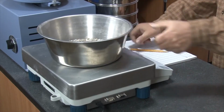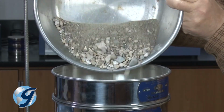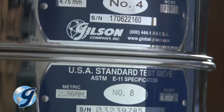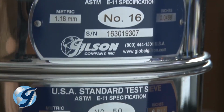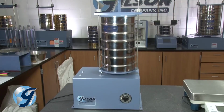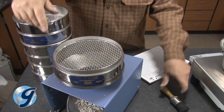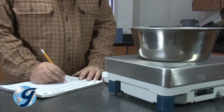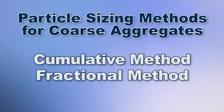A dry representative sample of material is weighed and then is placed in the top of a group of nested sieves or screen trays, arranged in descending order from the largest openings at the top to the smallest at the bottom. The stack is agitated manually or using a sieve shaker for a designated period of time, and the operator weighs the material retained on each sieve using one of two methods: the cumulative method and the fractional method.